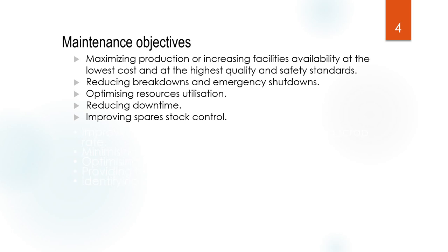Okay, and for reliability, it is the probability of keeping the equipment running without failure. Like when we talk about reliability of the equipment being 90%, that means its probability of failure is 10%. That means we can keep this equipment running without failure 90% for this period, and it's different from period to period.